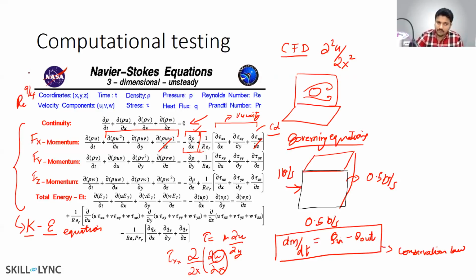You can assume that this is roughly Reynolds number to the power 3. It's not accurate, but it does the math for us. If your Reynolds number is 100, then you need 1 million cells to get all the scales, which is something that you can do very easily. But if your Reynolds number is 100,000, it's pretty much impossible to do a direct numerical simulation.